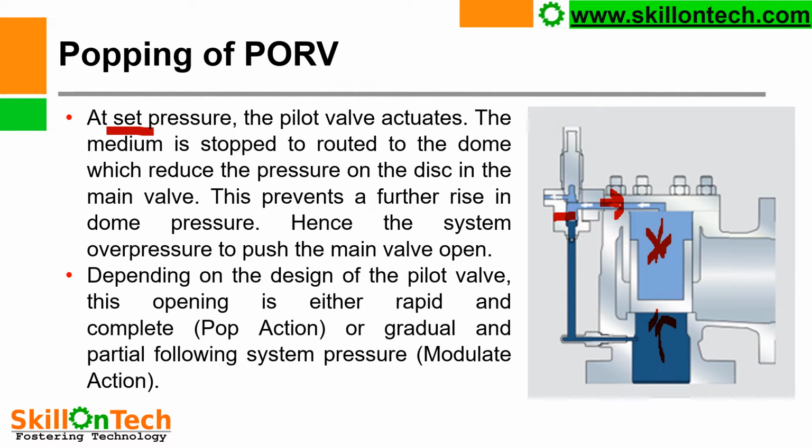and depending on the design, pressure will be released through the outlet port. Depending on the design of a pilot valve, the opening is either rapid and complete pop action or gradual and partial following system pressure, modulate action. Means a partial opening of this main valve seat and release of pressure here.